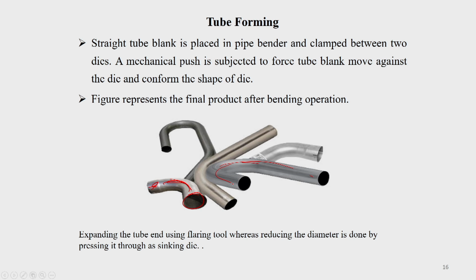But remember, when you are bending the tube, there is every chance that it may collapse at the bend. So, you have to do it effectively, so that it is uniformly bent without collapsing.